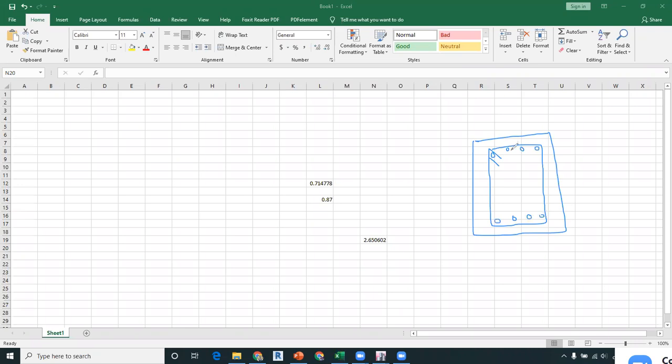So you can provide your legs like this. This is the first leg, and this is the other leg. There are different arrangements you can do for your design, right? So in our case, we have selected 2 bars, 3 bars for the bottom, and 4 bars for the top, right?